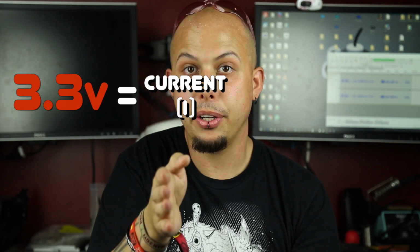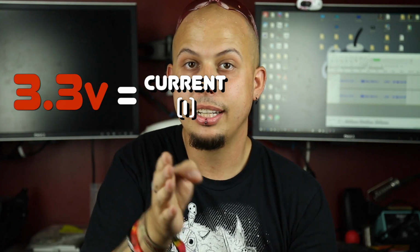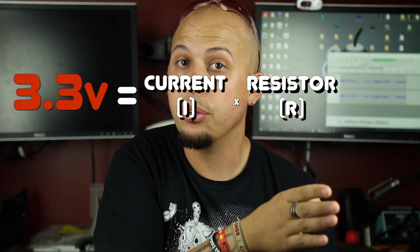For example, our 5-volt system minus the forward voltage of a red LED, 1.7, gives us a voltage of 3.3. That's what we have to resist, not the 5 volts in total, because it's not actually going through the circuit. So now we have a 3.3 volt system equals our current that we want for our LEDs, times the resistor that we need to choose.